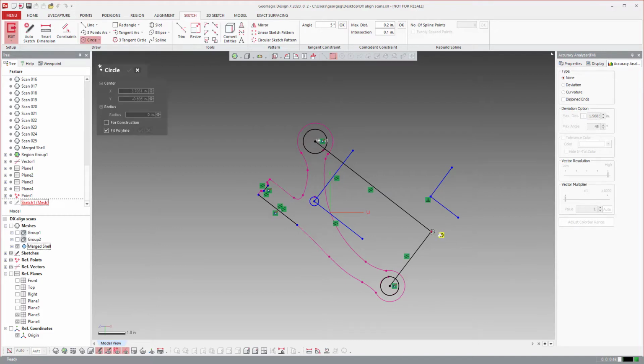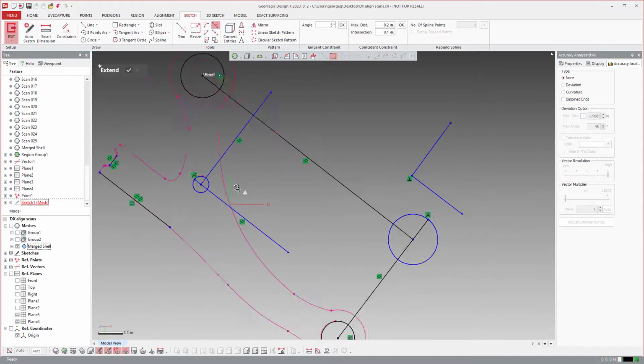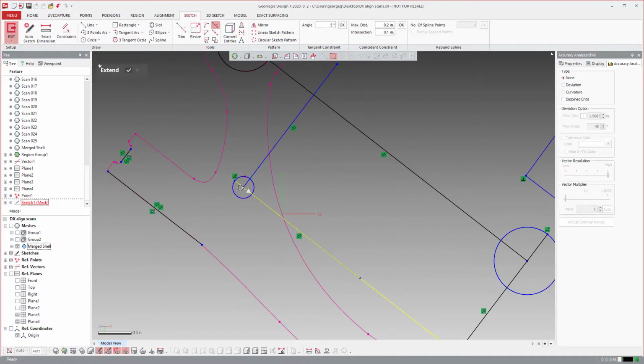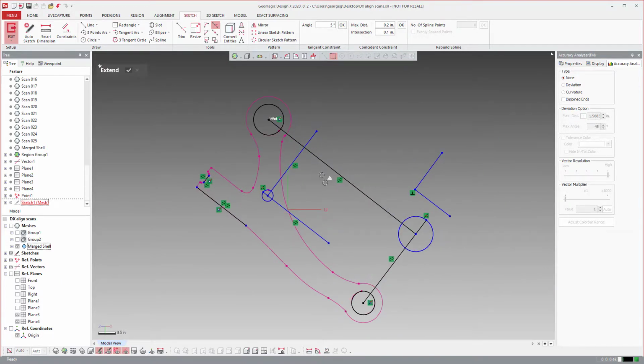So one thing that I'll do is I like to put a circle around it and then I'll extend one side like that. That way, that's where my 0 is going to be. And then you'll see in a second why I do that. And so the advantage of this one, as you can see, is 0 doesn't have to be anywhere on the part. I can draw 0 and square things to whatever I want them to be squared to. So I could put 0 right here or right there.